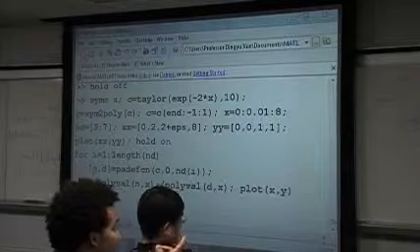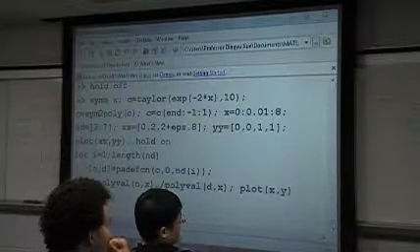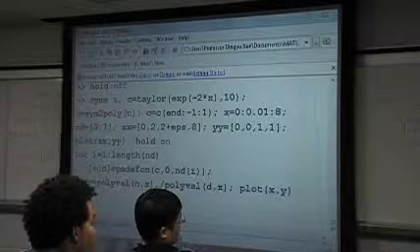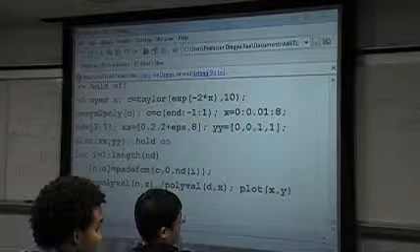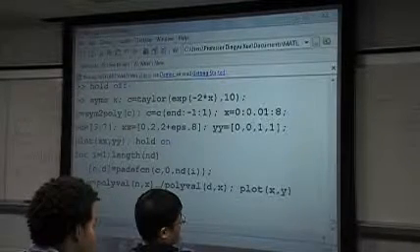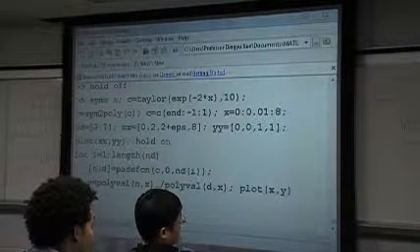So leave it like that? Yeah. In Matlab, if you use the tf function, you have to specify n and d, and also you can specify I/O delay equals to T. This is an acceptable Matlab object.